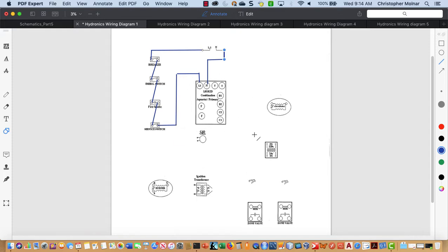So the easiest way to do this and show this is we're going to come over here. I'm going to take this line. Okay, now when you're in someone's basement, this is either in a junction box or it's tied to L1. Most likely there's a junction box where this switch is, and everything will come off there.